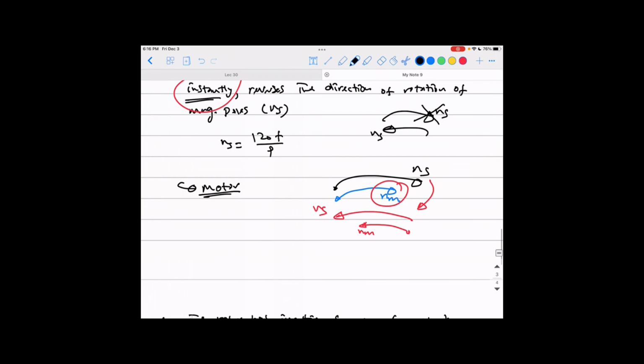Because you'll have just this synchronous speed is now reversing direction to go this way. So it will try to drag the rotor also in its direction, okay? So it will just cause like a brake on the motor. That's why we call it some sort of an instant brake. But it will not be instantly, making the motor be braked in zero time. No, it will take some time because still the motor has some inertia to it. Okay? But it will slow down to zero and then it will just switch direction and go into the other way. Okay, guys?